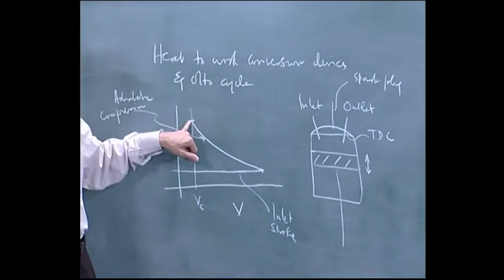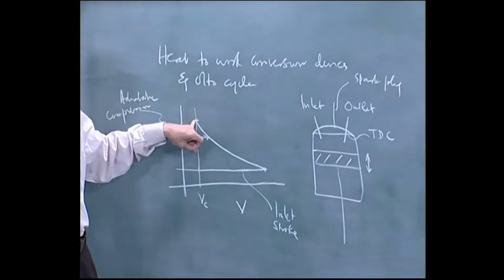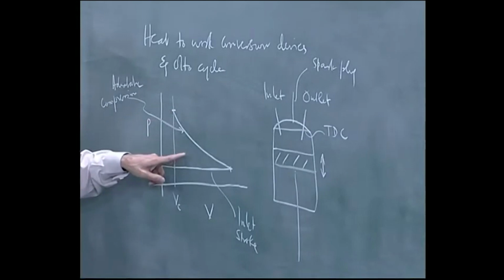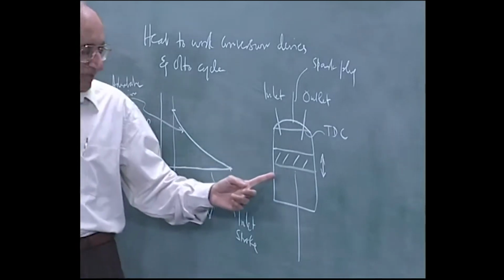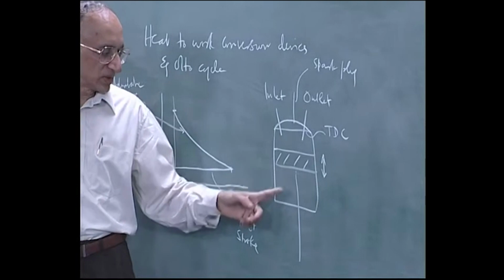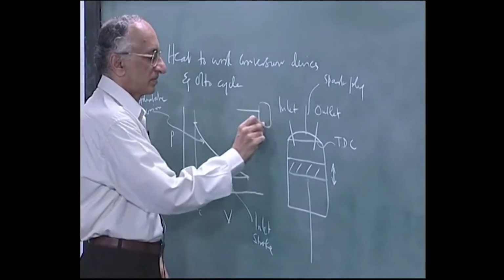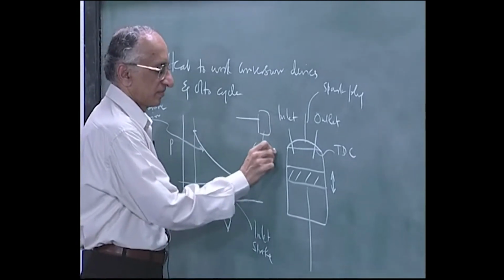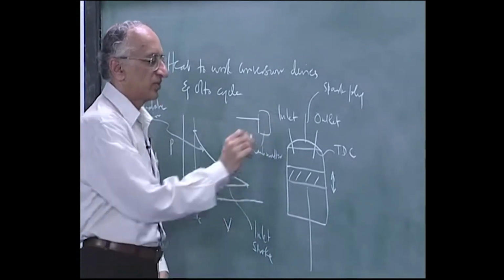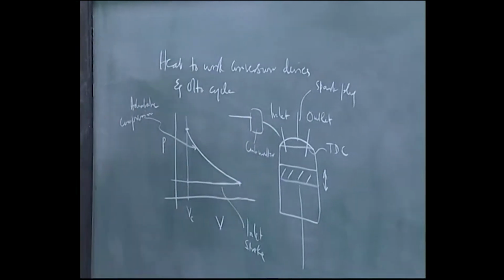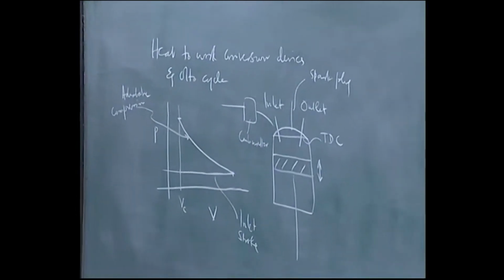Nowadays what you have is an injection device that injects the fuel as well, because it measures the fuel exactly. Normally in the classical engines, and we still have a few of them, the air comes in through a carburetor. The word may go out of the dictionary soon, so you may not even need to know it. What the carburetor does is measure the fuel: if you put your pedal to the metal, then a lot of fuel will be taken in. If you relax on the accelerator, only a few drops of fuel will be taken in. That is controlled by a beautiful mechanism.